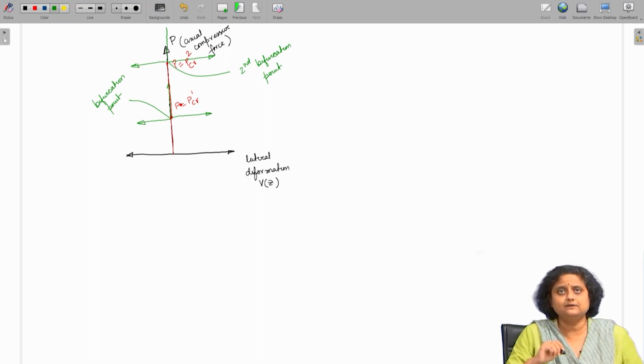There is this instability, it is most likely going to fail. But if it does not deform, then we can further increase the load and go to the second critical value, P critical 2, where again a bifurcation point happens.